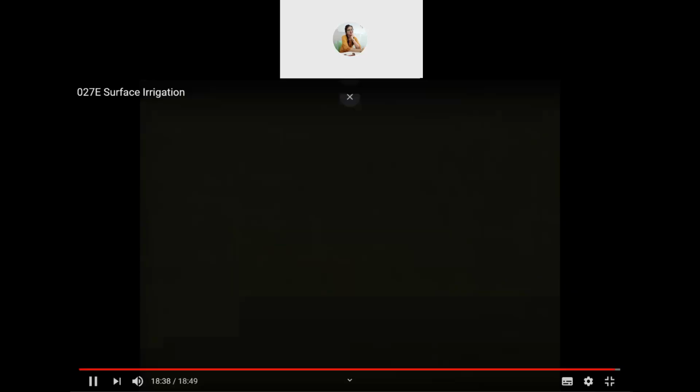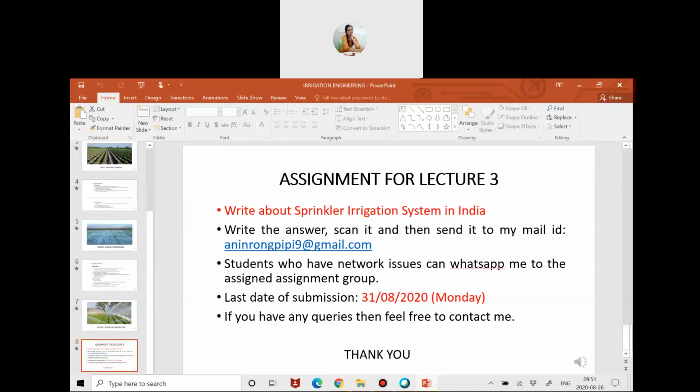There are three things which determine the flow rate into a furrow: the number of siphon tubes into each furrow, the diameter of the siphon tubes, and the height of the water in the canal above the outlet of the siphon tube. Usually, you will know the number and size of siphon tubes you will use before you begin an irrigation, but you can adjust the height of the outlet of the siphon tube as you irrigate. By raising or lowering the end of the siphon tube, you can equalize the flow between all of the furrows, or give some furrows more or less water as needed.